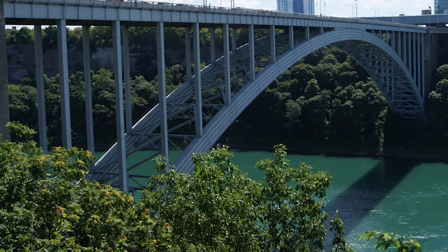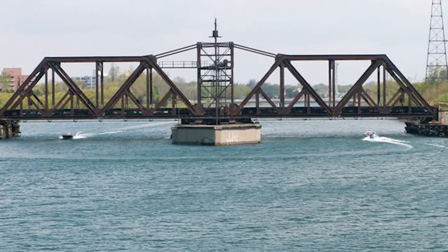Also in phase 1, you'll learn about truss bridges and how they work. For example, how certain members of your truss bridge will be in compression and others will be in tension. How for truss bridges, in terms of the height of the bridge versus the span, there is an ideal range of heights where the design will be as close to ideal as possible. How in terms of your panels for your bridge, each panel needs to be triangulated for the bridge to be stable.